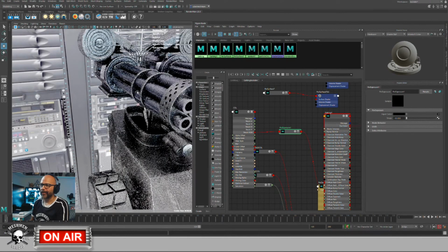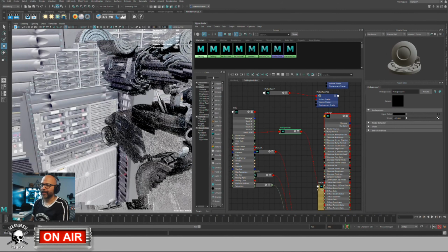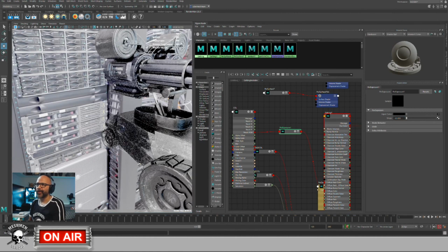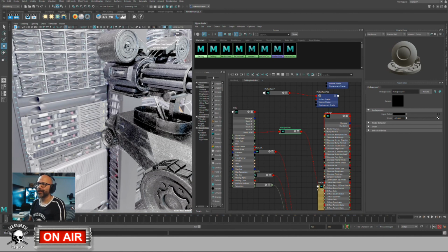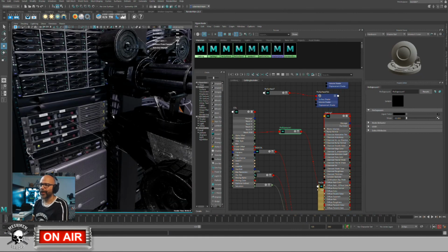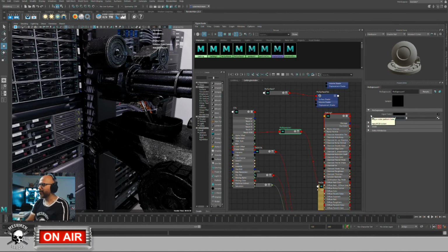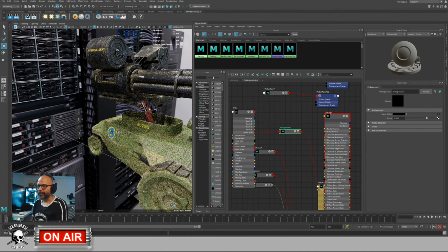You can see here now essentially this one will not behave properly, and sometimes you get a texture and it's really dark and you might need to raise it. In my case here, I already painted it in the correct values because it's derived from Lookdev. So I just want to demonstrate something. If you overexpose your gamma and your exposure and something in your render is still not behaving appropriately with the lighting, it's usually something that you need to either grade or bump back to texturing, because you might have something that's totally just 0 in value, and that's usually not a good thing to have, because then it will start to behave incorrectly when you start to light it.